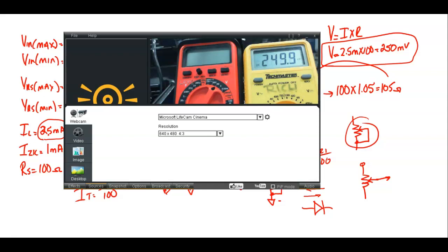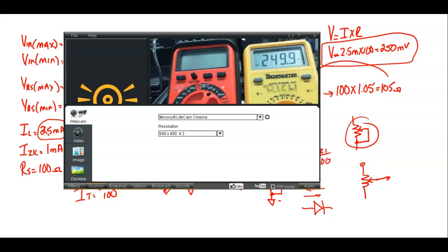And this is a technique that we use all the time. If I've got a resistor that I can measure across, instead of breaking the circuit and measuring amps, I am going to measure across the resistor and calculate current. Why? Because otherwise you have to break the circuit and measure amps, right? What's nice about using a 100 ohm resistor is you just measure the voltage and move the decimal point to the left twice, and automatically you've got the current flowing through it. Everybody okay?